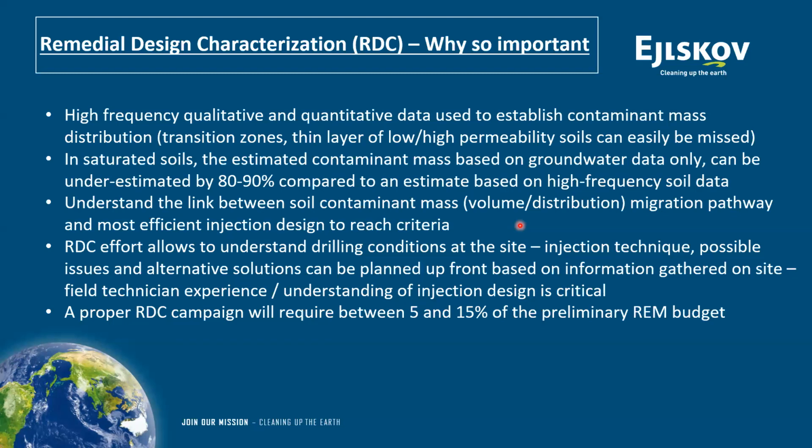The other benefit of doing an RDC is that before going and doing an in-situ remediation, normally as we do by injections, we can understand the drilling conditions at the site. Sometimes it's not straightforward to be able to drill by direct push into a specific type of geology. So by being there ahead of time and starting to do some drilling, we can figure out if we need something different to be able to then complete the remediation down the road.